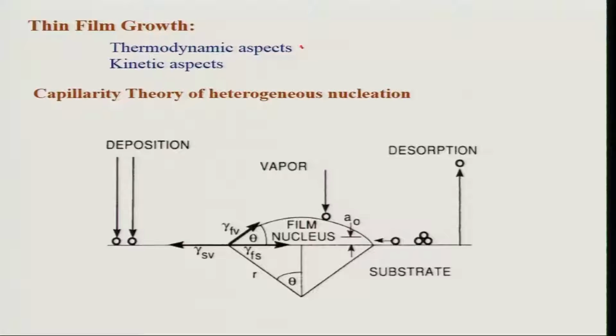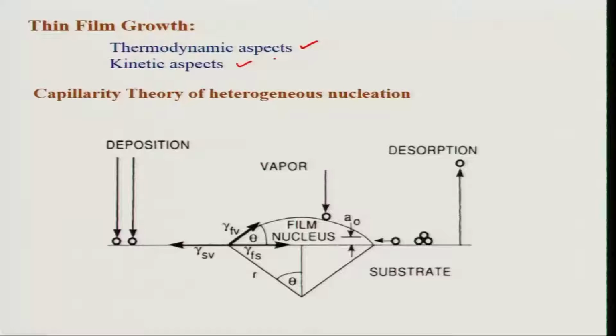Okay. So, while discussing thin film growth, we will discuss two different aspects. One is the thermodynamic aspect and the other is the kinetic aspect. Okay. Thermodynamic aspects are more like equilibrium aspects and it depends on energy. Kinetic aspects, on the other hand, relate to the rate of change. Okay. So, first we will discuss thermodynamic aspects, and in this we will discuss capillarity theory of heterogeneous nucleation.